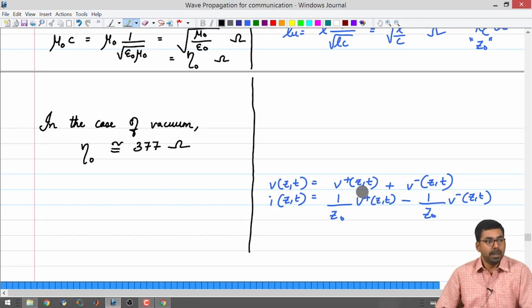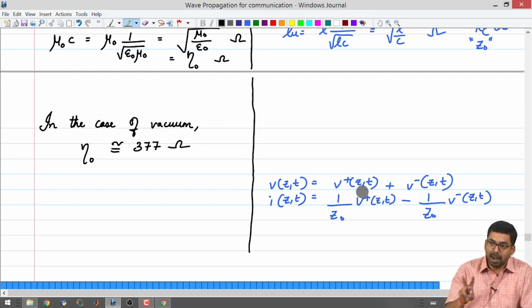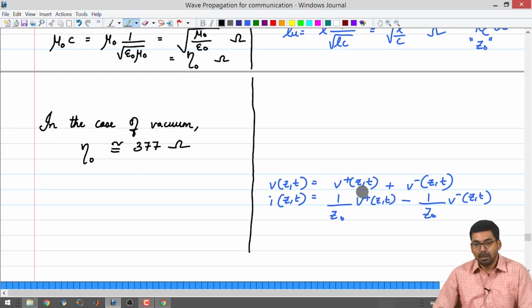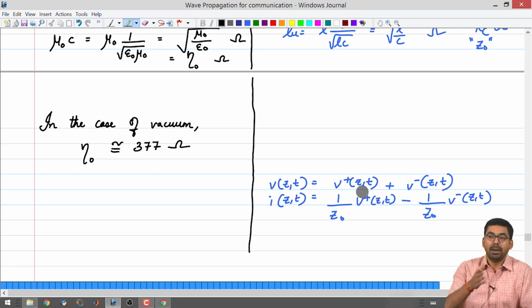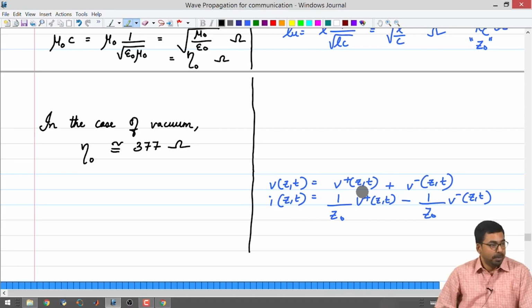The fear of Maxwell's equations should go away. The most important equations are the two curl equations, and for us the two curl equations are just the two telegrapher's equations. But then what about Gauss's law? Why is that plugged in? Why are there two more equations, and how do I draw an analogy between that and the transmission lines? Could be a question to ask. The answer that I always give is, do not worry about it for now. Those are known as implicit boundary conditions. We will get to that a little later.